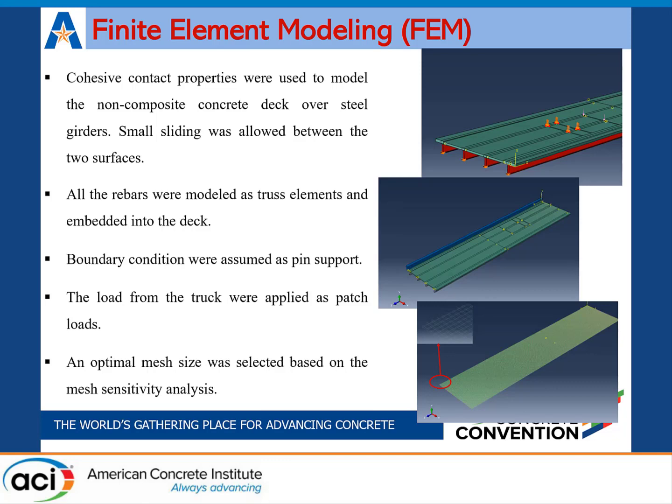So a full-scale bridge model was prepared in Abaqus software. Cohesive contact properties were used between the girder and deck interface. Rebar were embedded in the deck. Boundary conditions were assumed according to the field support. Then the load from the truck was used as a static patch load, and optimum mesh was selected based on mesh sensitivity analysis.